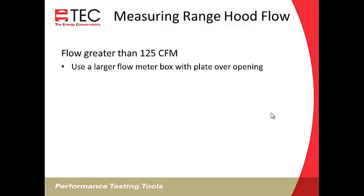For flows greater than 125 on a range hood, you can use that larger flow meter box like we talked about. Fabricate one that's 1.5 times the opening, and cut an opening just smaller than that in the plate, and cover that over the opening to get measurements larger than 125 CFM. And it is important to have that depth.